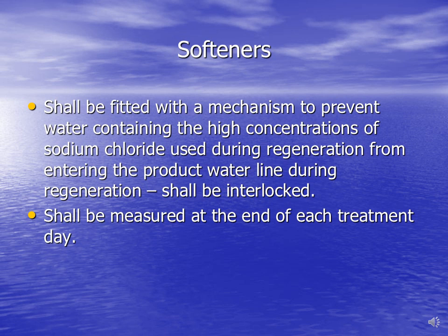And typically, it can take anywhere from maybe 35 minutes to an hour and a half, depending on the size of the system and the type of contamination of sodium into the system, to flush out all that sodium back to a level where the RO system can now generate product water that is low enough in sodium content to be used for dialysis. So during that time, your patient is not dialyzing, and hence the indirect impact on your patient. They're not dialyzing for a long time.